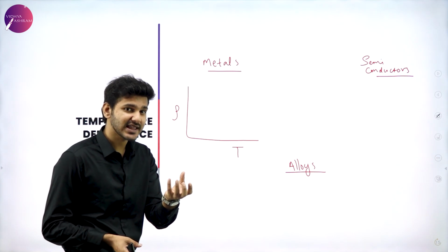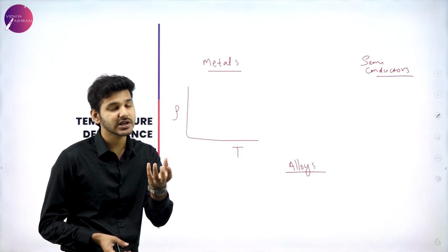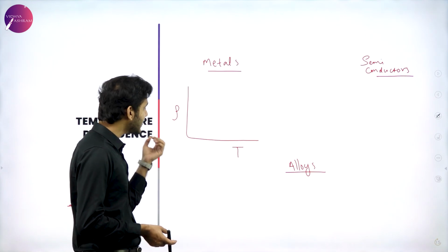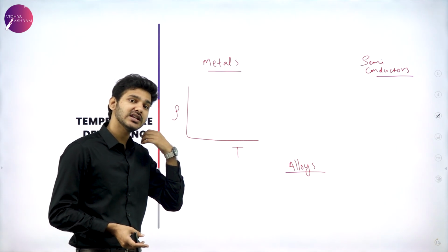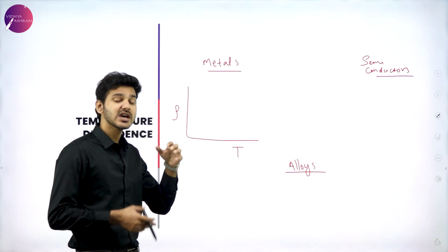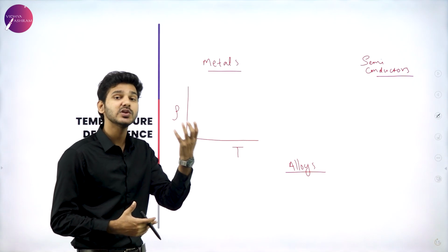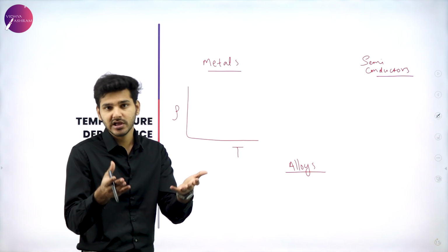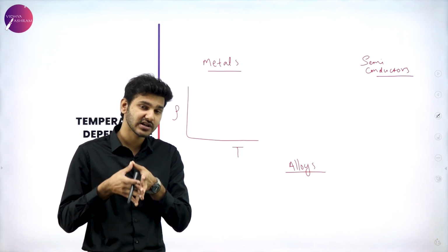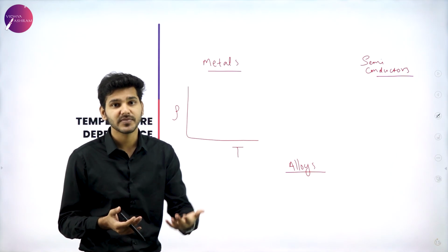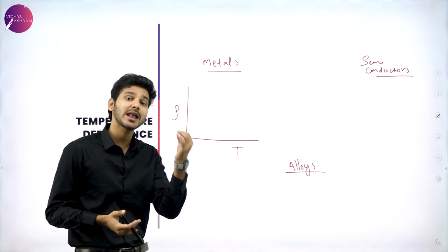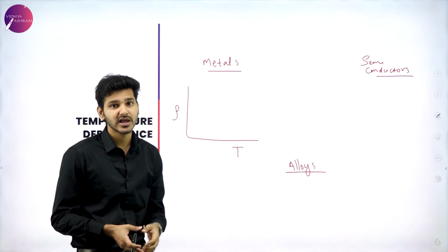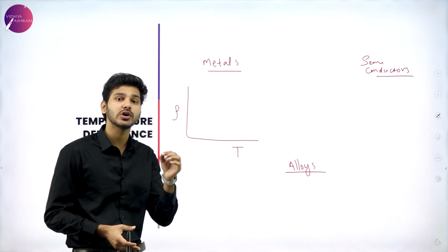We use tungsten in that bulb so that when we increase the current flow, that is, when we increase the temperature in that system, resistance increases, which is why the bulb glows extremely red. The heater you use at home also, when we increase the current, the temperature automatically goes up, and the material starts to glow red hot, even yellow maybe. That is because resistance is going up.